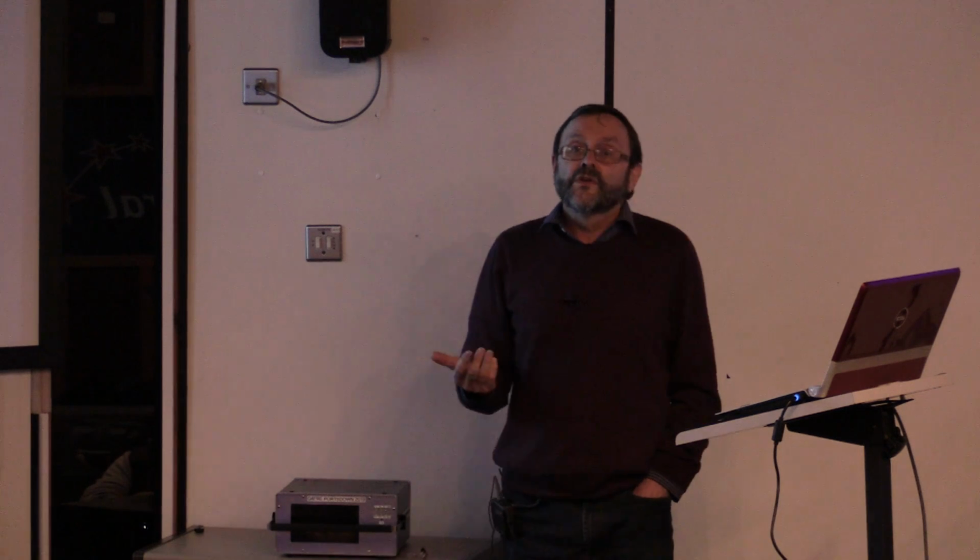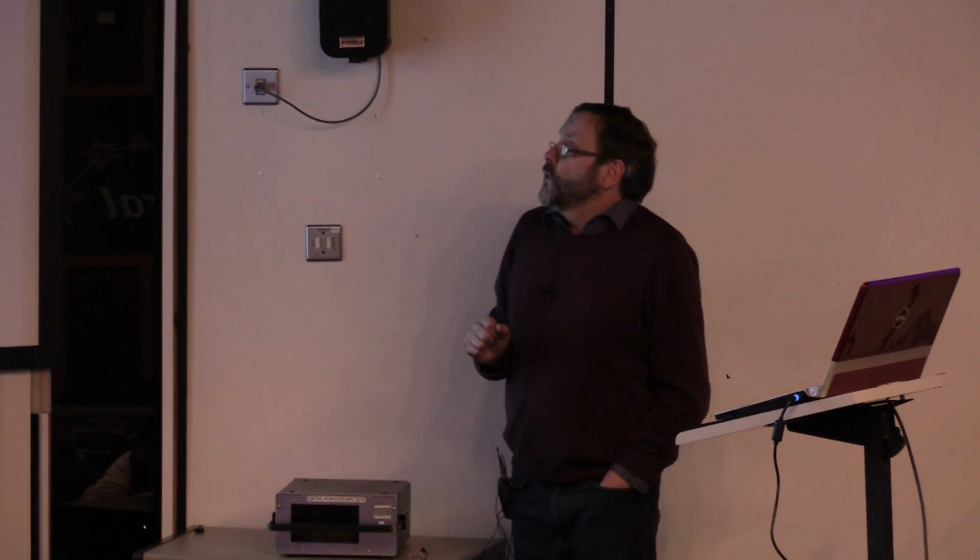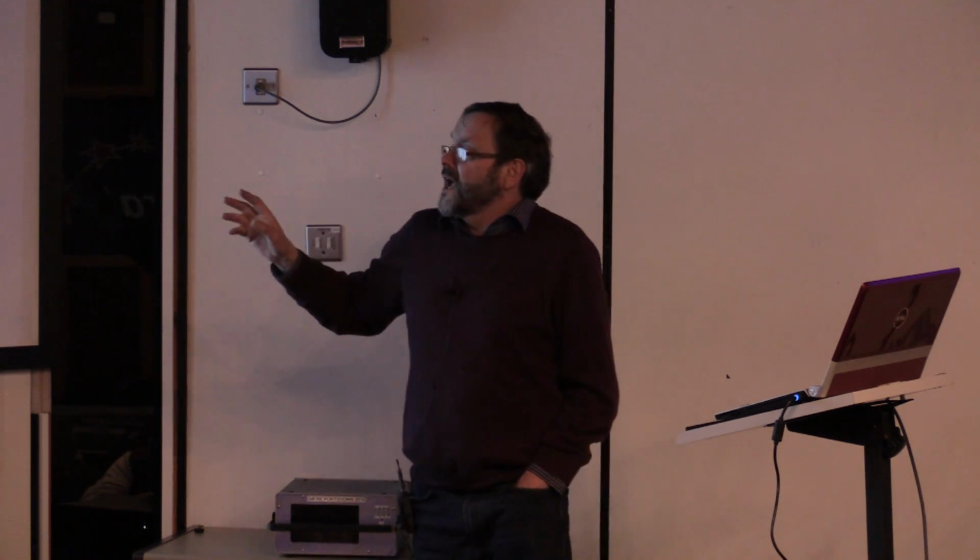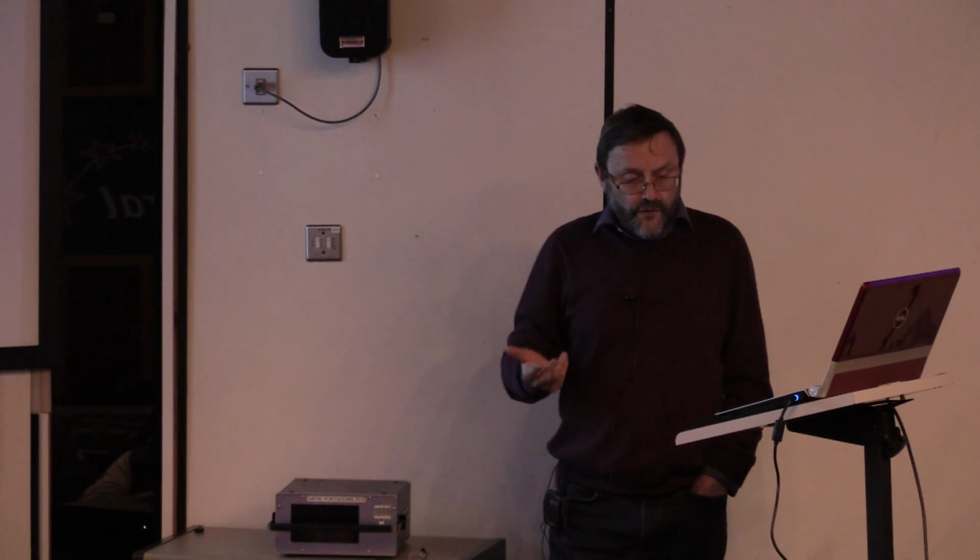So a standard LNB puts it down at 741 megahertz, which means you can't use a standard set-top box as it stands. So what do you do? Well, you can modify the LNB such that the local oscillator now produces an IF output which is in the range of the set-top box. You can up-convert the signal to L-band, and David showed the AMSAT-DL box which will take the 741 and convert it up to L-band. Or you can use a different USB tuner.